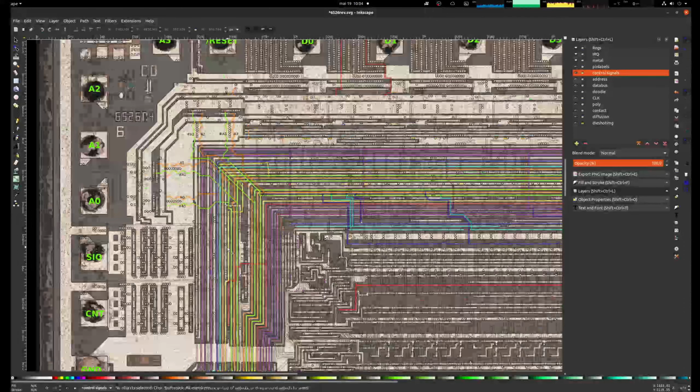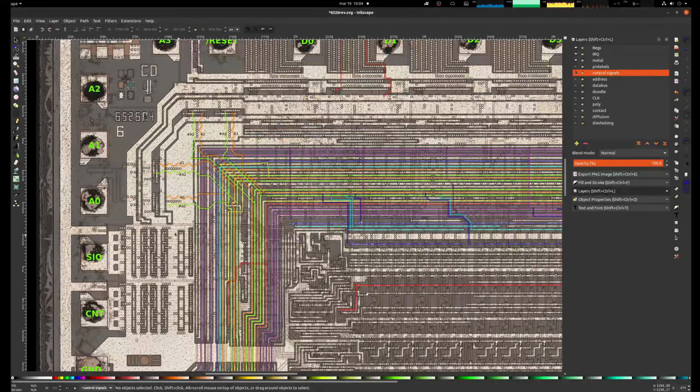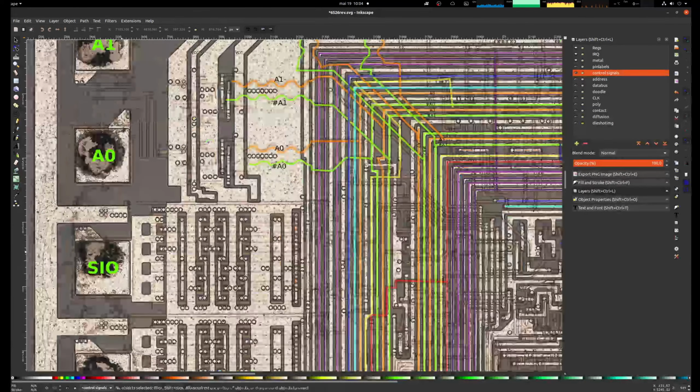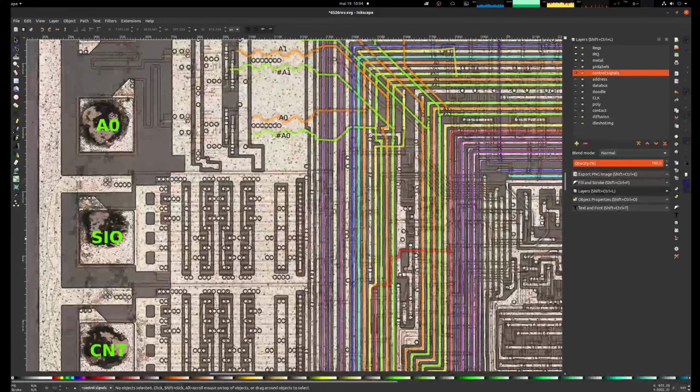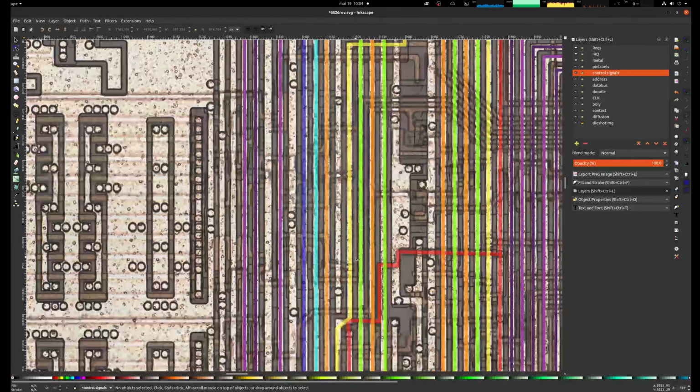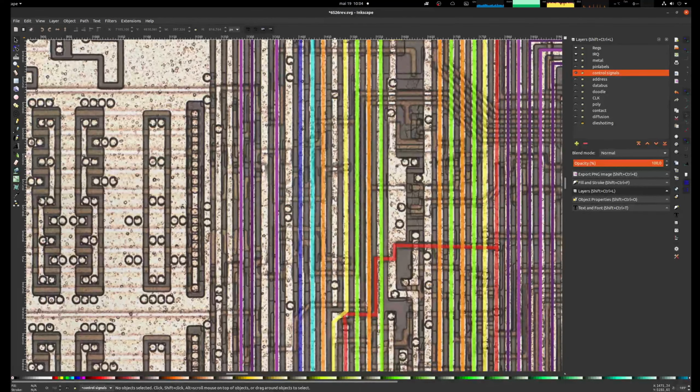What is it doing? Yeah, so it basically acts like an enable for this large output driver. And you can also see, you don't have to disable an input, but you have to disable an output driver. So here you have to see the input of that pin, serial input output. And it has, I think, it taps off in two places, like there and there.